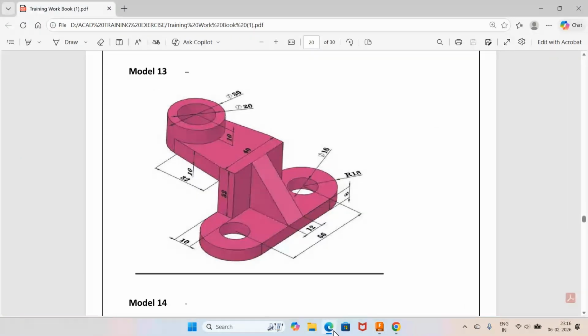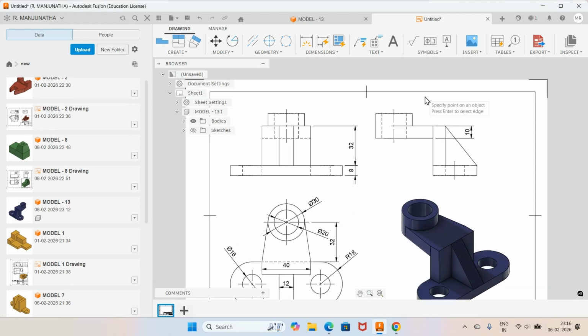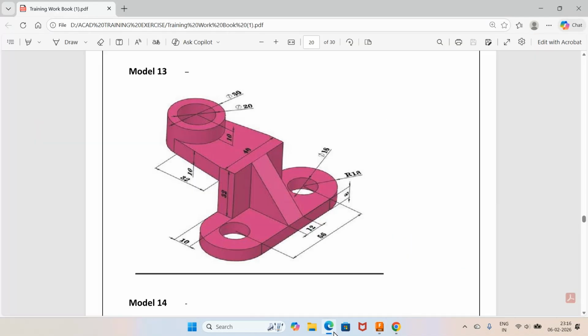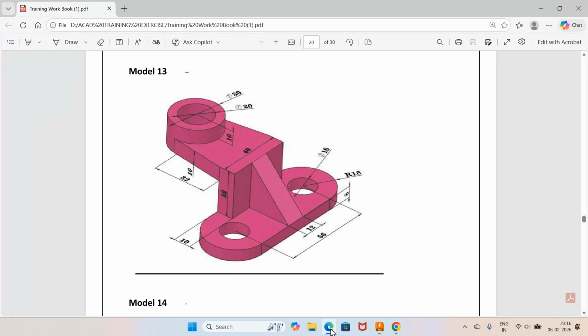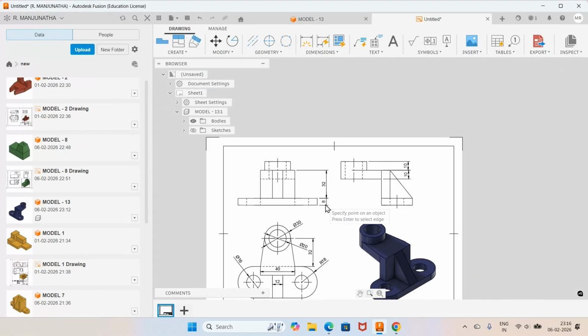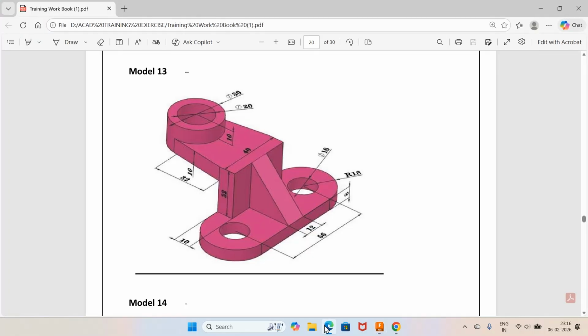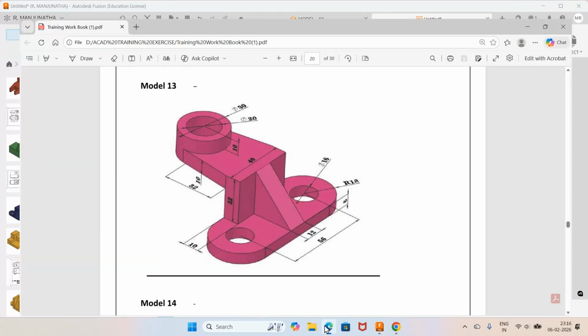Once you do that, 32, 10, 10 is over, this 32, diameter 30 and 20, that is also over, and this dimension to be 10. We just take between this dimension and this dimension, which is 10. Once you do that, all the dimensions have been covered here. Then you take the thickness as 8, that is done. Then this thickness is also 8, that is this distance, or it is 8 or 10, it is 10. Then this height is also 10. This is diameter 30 and 20.